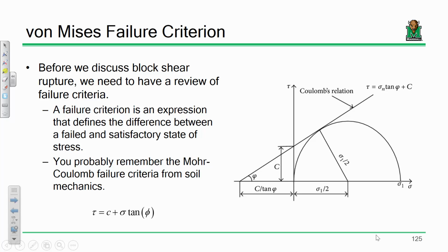So, for instance, and this will become an analytical problem for you in soil mechanics, sandy soils are cohesionless, so you'll take the C value to be 0 and stuff like that. You will do this in soil mechanics. You probably have it now. You will, I promise.